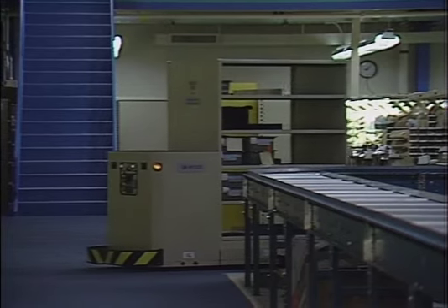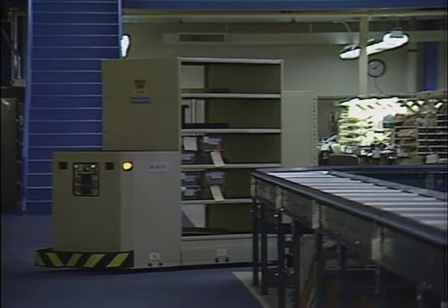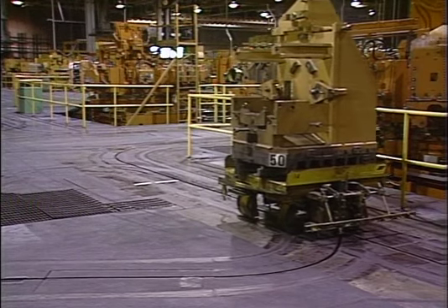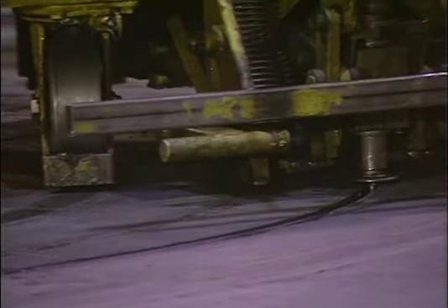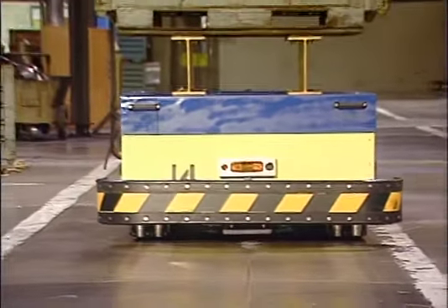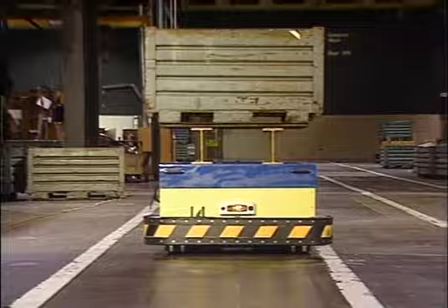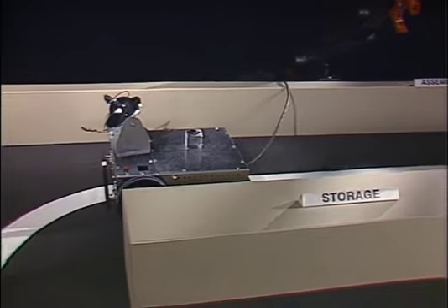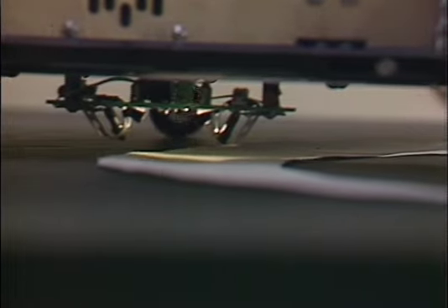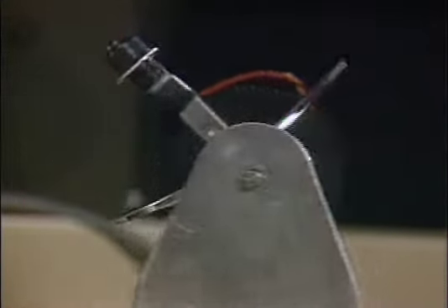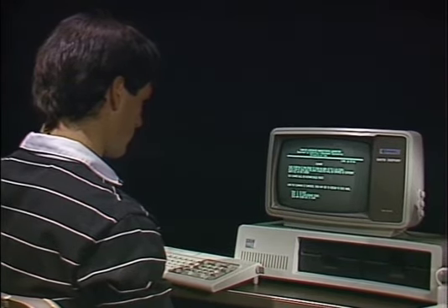The materials handling function may be automated with automatic vehicles capable of moving around in the plant and transporting materials between workstations. Automated guided vehicles, or AGVs, may be guided by chain drives under the floor surface, magnetic stripes, or signals transmitted in wires on the floor. The laboratory includes a scale model of an AGV that can follow bright tracks on a dark background. The AGV has a scanning mirror to focus environmental light on a photosensitive element. The signals are processed by a host computer, providing vision for navigation.